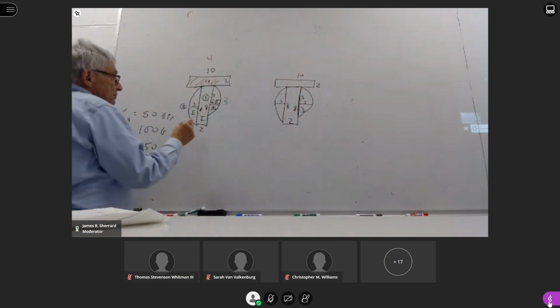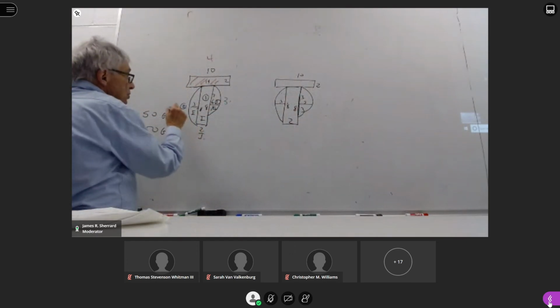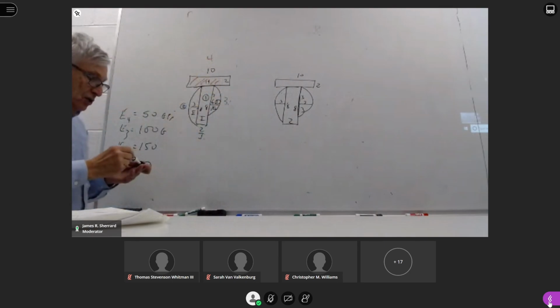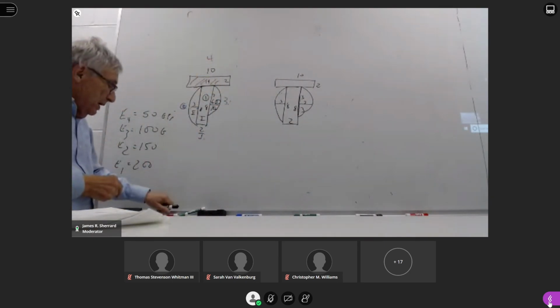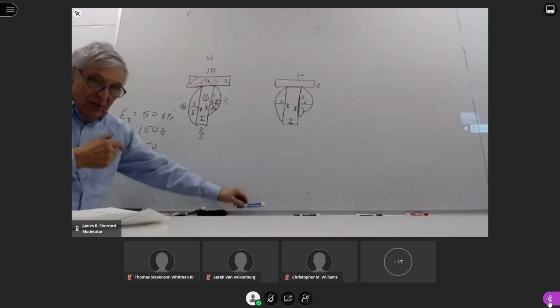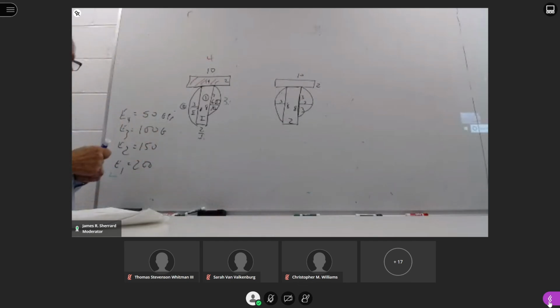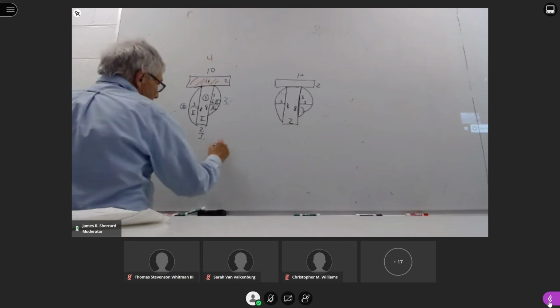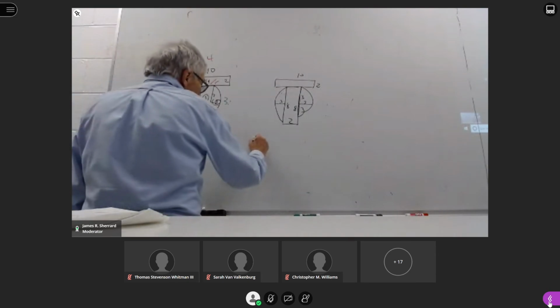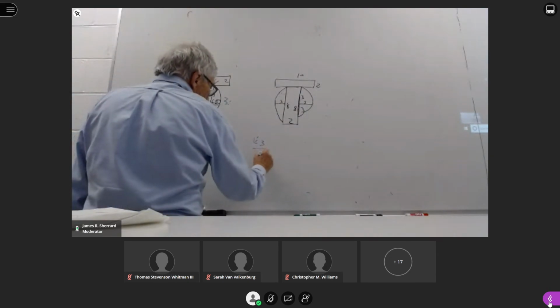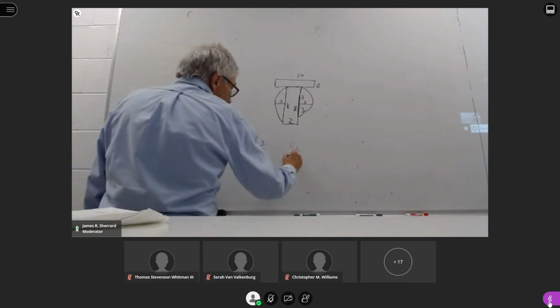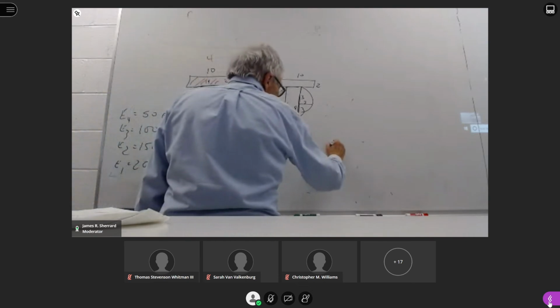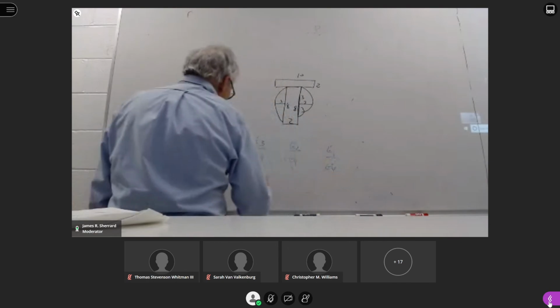Okay. And we know we have sections 1, 2, 3, and 4. Whenever you do this, you pick a common denominator, and then you make that cross-section be all that material. So in this case, I would pick E4. So I'm going to look at E4 to E4, E3 to E4, E2 to E4, and E1 to E4.